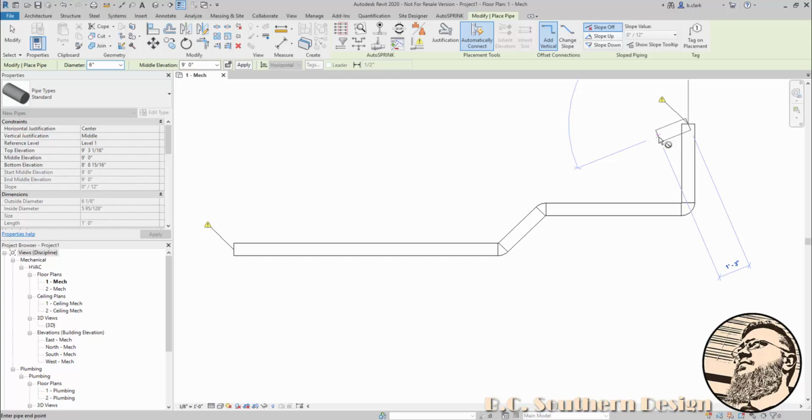So here are your two methods. One allows more freedom, so you can snap to those common angles, but also draw, I don't know if exotic is the word, but more uncommon angles for your fittings if you're fabricating those. But if you would also like to limit your angles to something very specific and not allow the more uncommon angles, like if you're not fabricating your fittings, so you're limited to whatever angles these elbows come in, then you can do that through the mechanical settings.